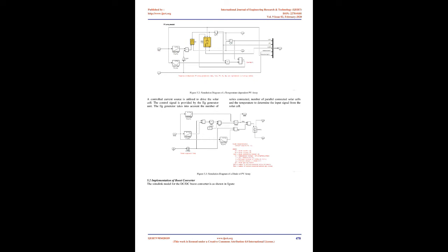This algorithm is not suitable when the variation in the solar irradiation is high. The voltage never actually reaches an exact value but perturbs around the maximum power point, MPP.